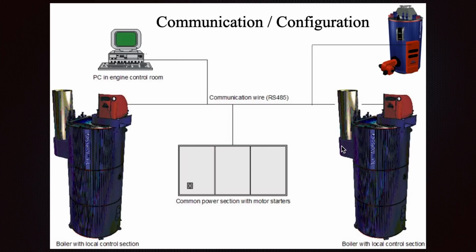The timing depends on the weather conditions, the engine room temperature, and the surrounding temperature. If the weather gets colder, the boiler starts more frequently, and if you also have consumption on the deck, your boiler also starts frequently, and you need to see how you will keep the adjustments and the settings.